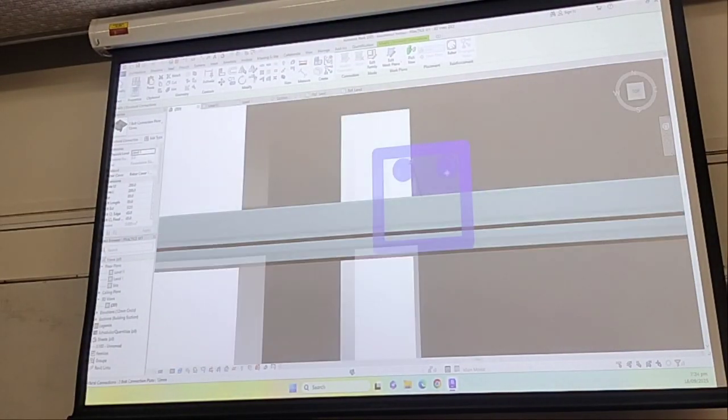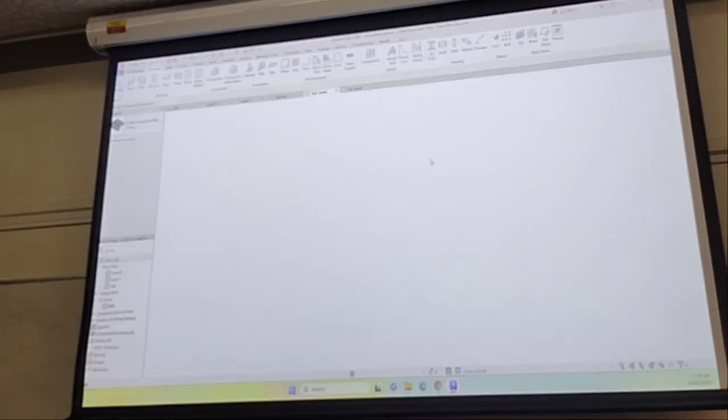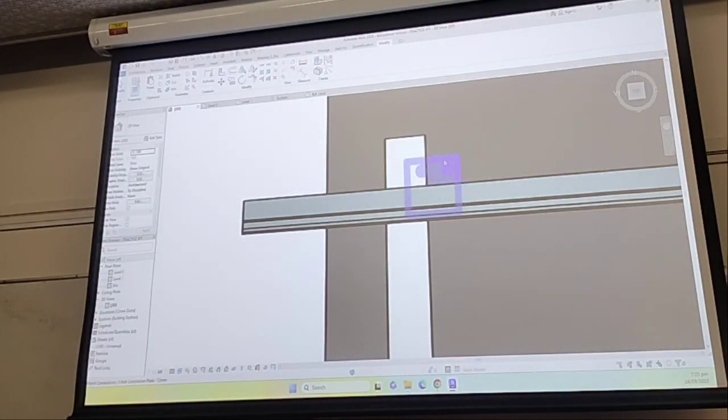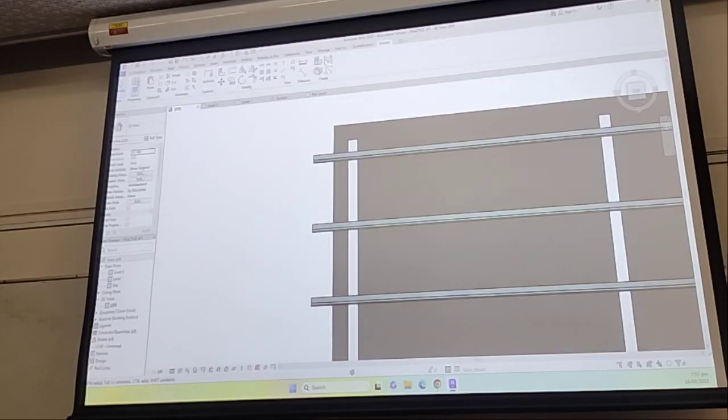And then putting the column on level 1 here. This is my level 1. It's automatically going up there. Like, see? Structure column, and there is 4,000, and there's 0. Yeah, wait. Let's change it to, first click level 1, use the level 1. And then this is the one I want. Yes, yeah. And now if I go on grid A1, it's not a good way to do it.